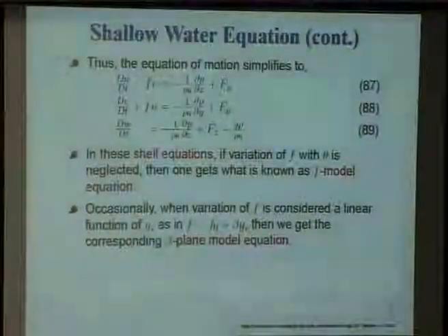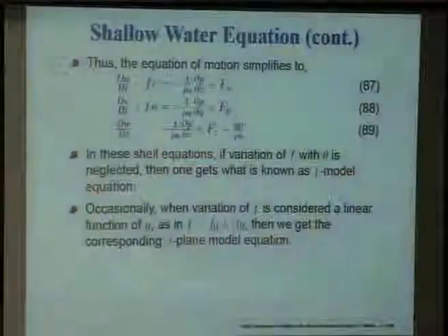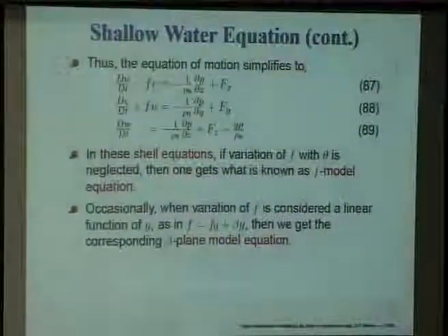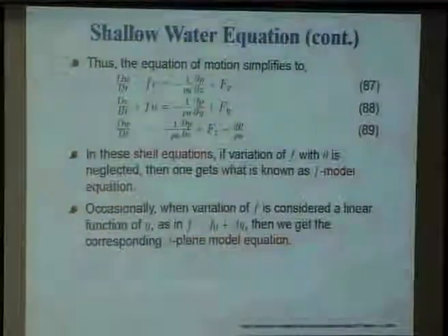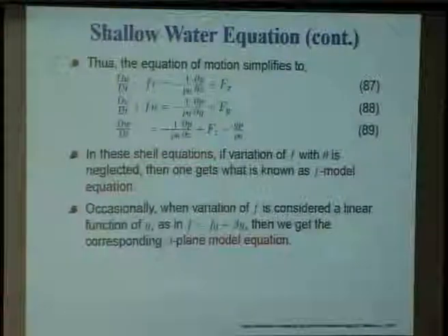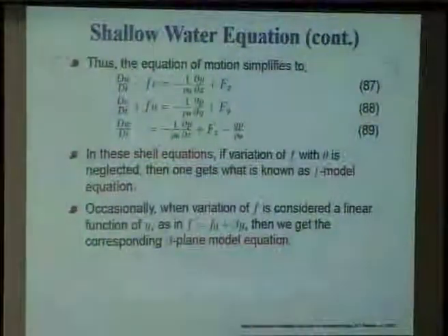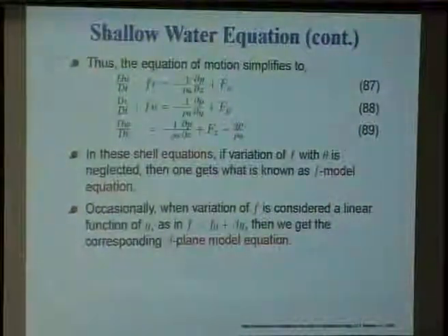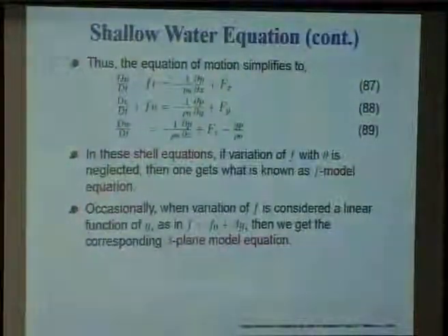Okay. So, what happens is we write down the governing equation now in this moving frame of reference. So, this is our substantial derivative of u, v and w, and we notice that the Coriolis term in the x component is minus f v, f u in the y component and nothing in the z component, and these are the pressure gradient term. This f x, f y, f z are those bottom friction that we have chosen, right.